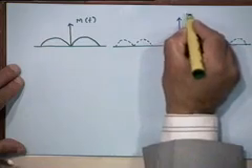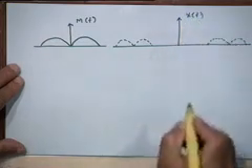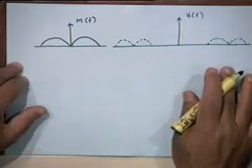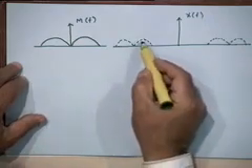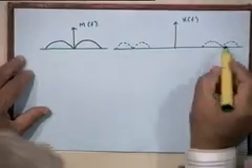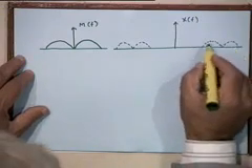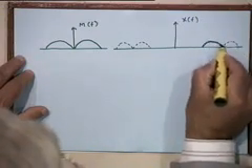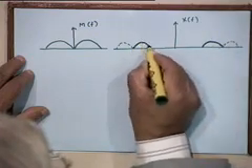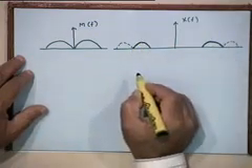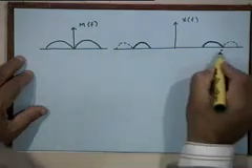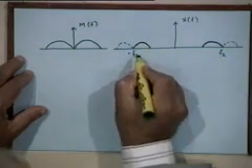So this is the normal DSB-SC spectrum. What we are saying is we can remove one of the two sidebands. For example, we could remove the upper sideband and transmit only the lower sideband. So we are transmitting this. This will of course come along with that. So this is around f sub c, and this will be around minus f sub c.